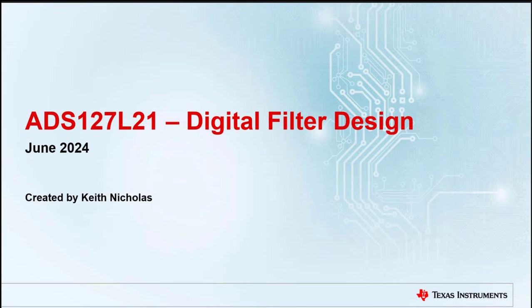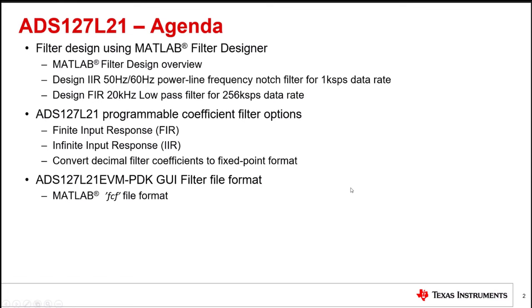And today we're just presenting a short video on how to create custom digital filters for one of our latest wideband Delta Sigma converters, the ADS127L21, using MATLAB and the ADS127L21 EVM GUI as a combo set to actually download the coefficients and then see the filter response and look at a few measurements.